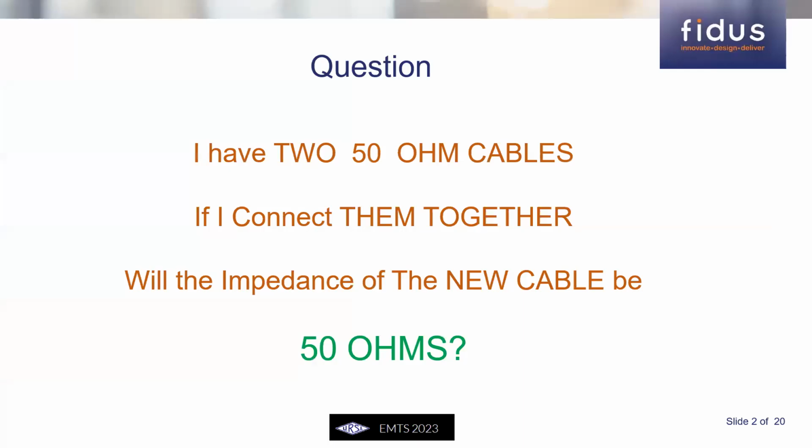So let's start with a simple question. This is something that is reasonably well known, but the impact of these assumptions is quite significant. I'm especially focusing on frequencies that are extremely high. So the current state of the art in PAM4 signaling is about 224 plus gigabits per second. So at those high frequencies, we're talking about Nyquist frequencies in the range of 60 gigahertz, and some things that we tend to take for granted become important.